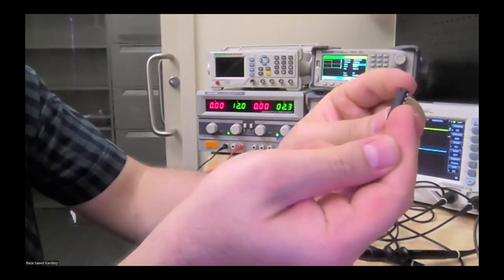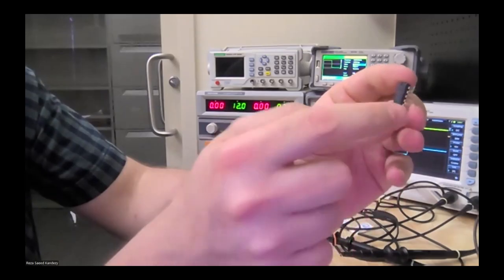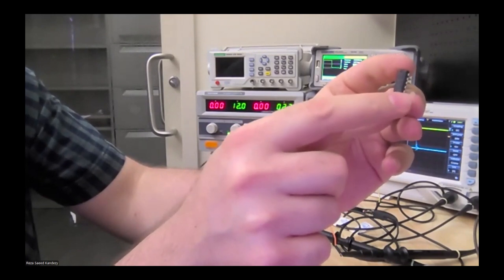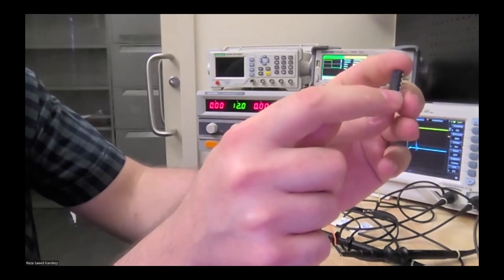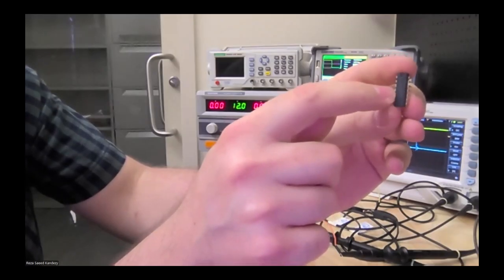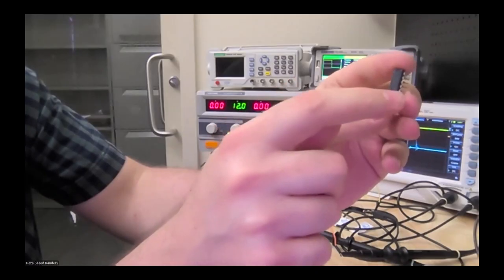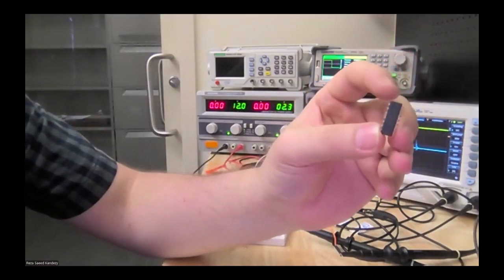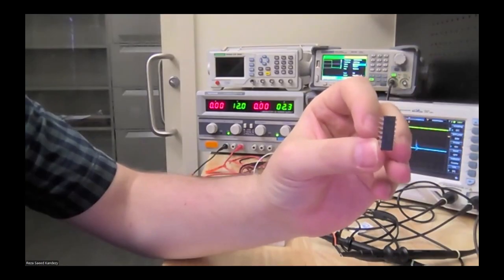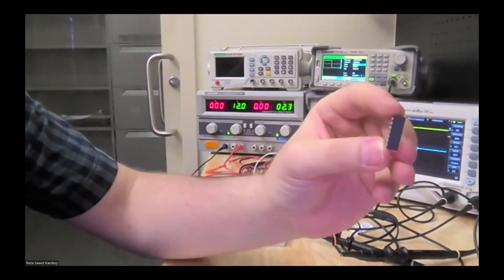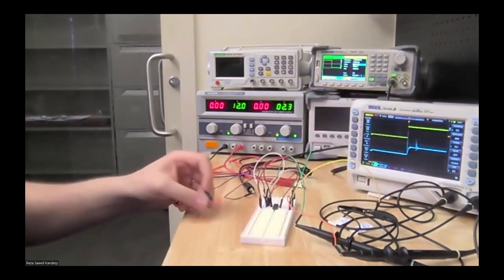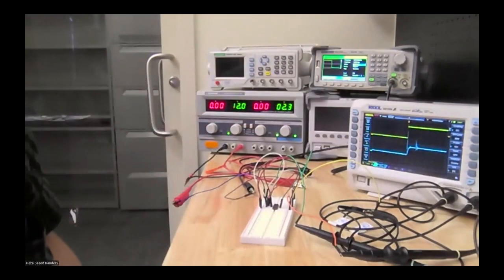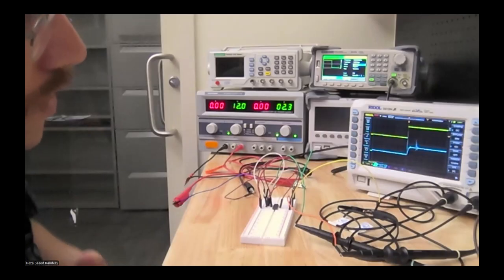Now, pin 11, which is 8, 9, 10, 11, the middle one on the right side, is ground. So you have to connect the fourth and the 11th, the two middle pins. The left one goes to the VCC, the right one goes to the ground. And then you have the unity gain buffer for one of the op amps in the LM324, which contains 4 op amps, to do the experiment. Now, as I said, I already set everything, and you can see that I measured the output and input.